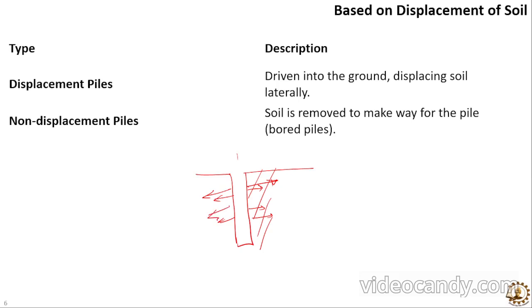And non-displacement piles are generally bored piles. That means we are not displacing the soil, but we are excavating the ground, and by excavating we are creating a hollow space, and we fill it with concrete or steel and concrete, and we create the pile foundation.